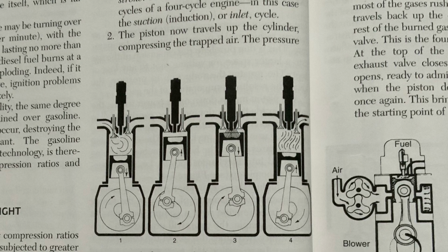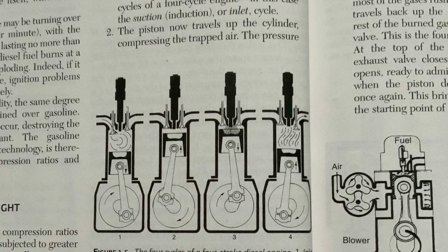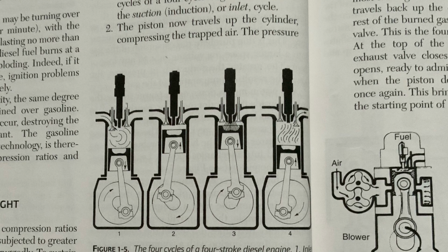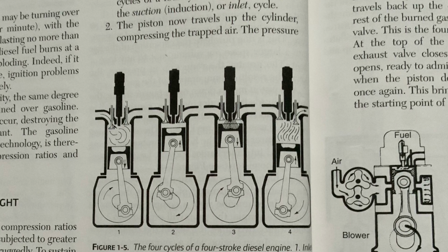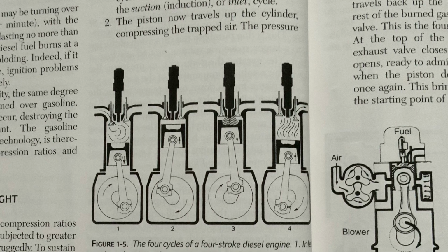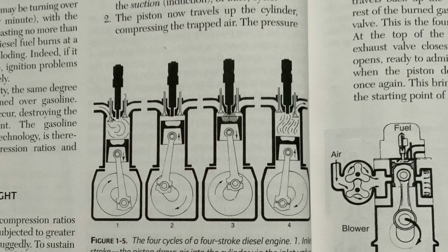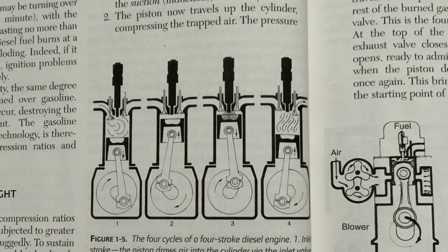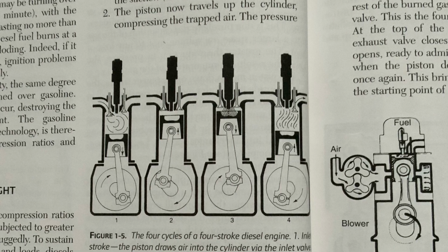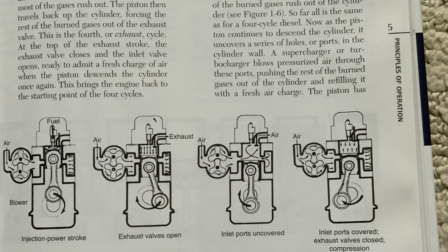A 2-cycle diesel. Note, the following is the description of the operation of a Detroit diesel 2-cycle engine, the most common and widely known type. There are engines with other forms of 2-cycle diesel operations, but such engines are unlikely to be encountered in small boat applications. A Detroit diesel 2-cycle engine operates in essentially the same manner as a 4-cycle engine, but condenses the 4 strokes of the piston into 2. Once up the cylinder and once down.